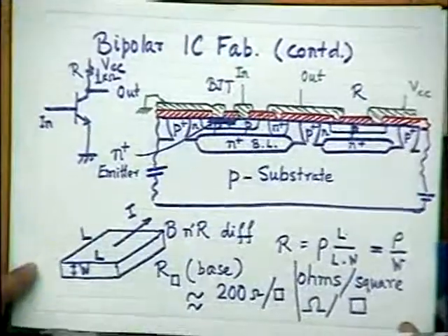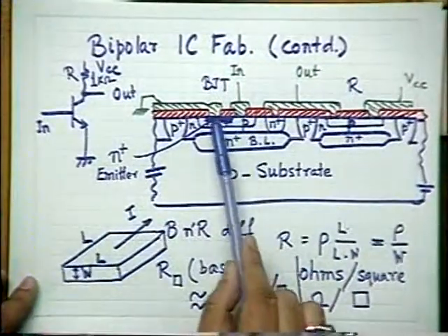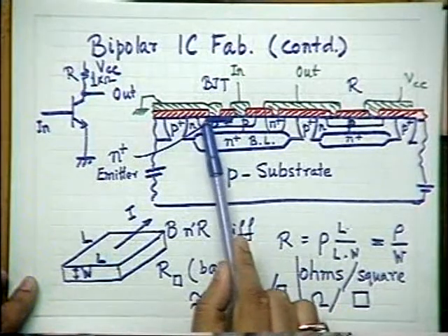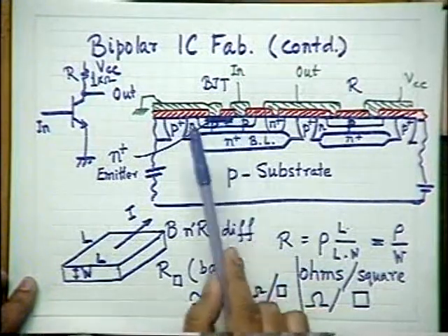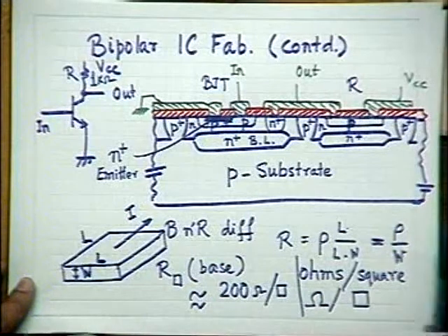But whenever you are interested in fabricating a high value of resistor, you are in problem. Can you tell me how we can realize a high value of resistance in a small region? No, actually a resistor called the pinched base resistor. Let me show you. Pinched base means between the emitter and the collector, this region is very narrow, you remember? The physical base width is very narrow.